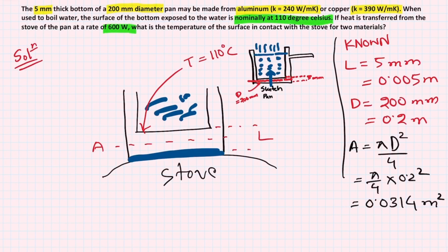two different materials, and all we have to do is use our theoretical knowledge of heat transfer, or conduction heat transfer to be more precise, to calculate this value of the temperature. But before doing that, we have to make some assumptions because we are going to use Fourier's law of heat conduction, because we know heat is being transferred through a solid material, which I am showing you with black lines, and because it's a solid material, heat must be conducted through it.